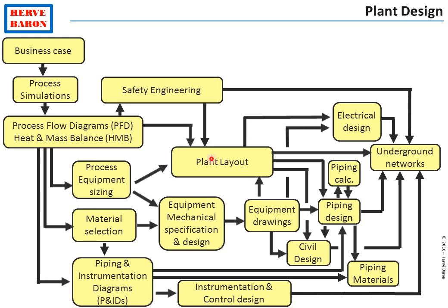One must be focused on the most important areas. Ordering equipment, finalizing the plant layout and the P&IDs, and attending to the critical path of the project with ordering of piping materials and issue of piping isometrics.